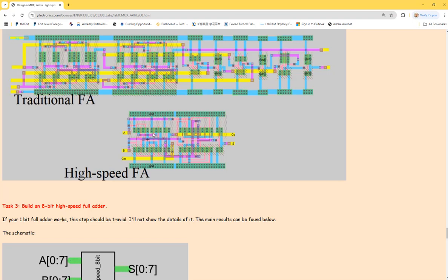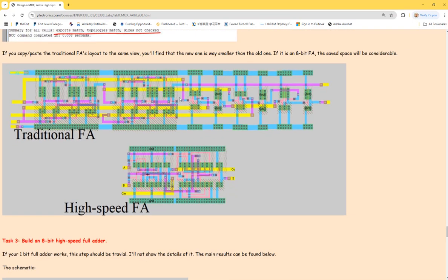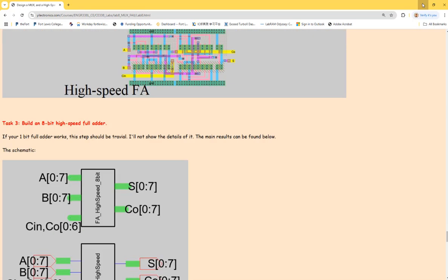Just looking at the rising edge of the circuits, this charges way faster than this one, which makes sense because you can see this has a lot of parasitic capacitors. Every transistor has gates, and it's charging and discharging all these parasitics, but this one definitely has less, right? Eventually you can tell it's saving a lot of space and also increasing the speed of the circuits. Right.